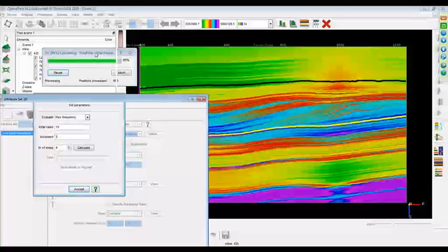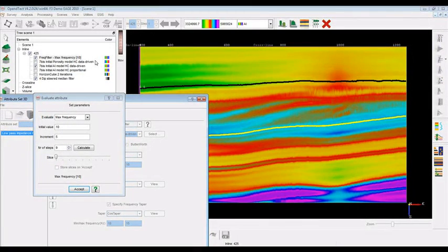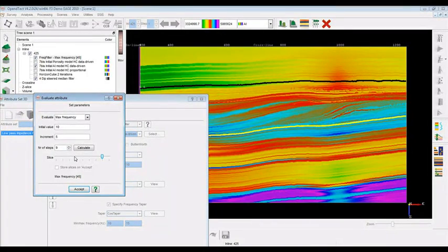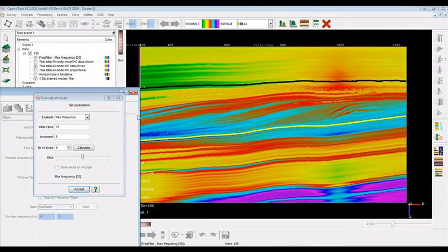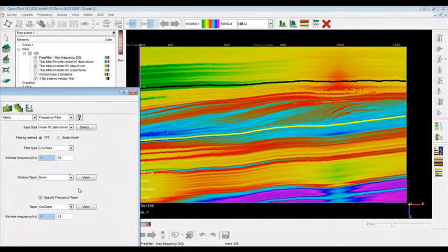So this is the output for 10, 15, 25, 30, 35, 40, and so on. But as you can see, even though we diminish the level of detail up to 30 Hz, we still have a very good following of the seismic reflectivities, and we still have all the benefits of having gridded the impedance logs using the HorizonCube as a guide.